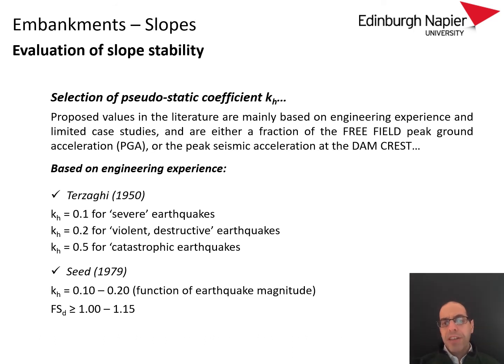Proposed values in the literature are mainly empirical, based on experience and on the very limited, well-documented case studies that we have. What you have to be aware of is whether those proportions are a proportion of the free field acceleration, i.e. something that is measured far from the dam, or the equivalent of the PGA that you are already familiar with as well, or whether those proposals are based on the peak seismic acceleration at the dam crest, because most of those dams, of course, are well instrumented because of their importance and the severity of their potential damage.